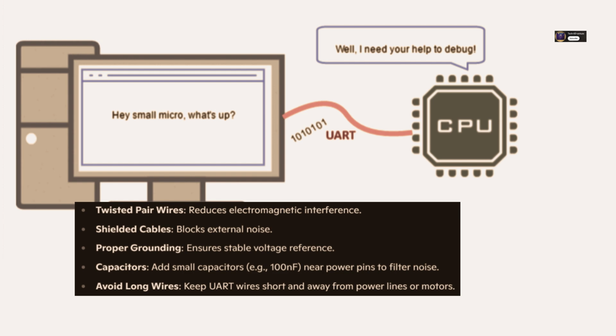6. Run the microcontroller firmware. Have it send a startup message like "MCU ready." Check if this appears correctly in the terminal. This tests MCU TX to PC RX. 7. In the terminal software, type a character or a test message and send it.